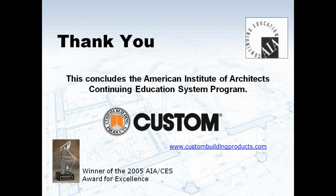Sometimes this person does large format tile, and the designer or homeowner wants a 1/16 of an inch joint in the tile, and it's not rectified. Do we deviate from the 1/8 inch? How do you handle that situation? What I always do, and I have designers who ask me the same question all the time, is say that this is what TCNA recommends. This is their suggestion for successful tile installation.